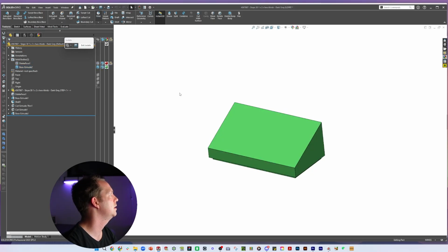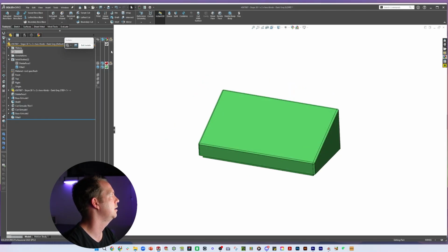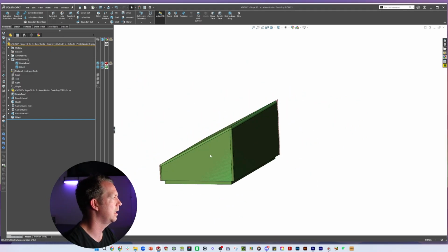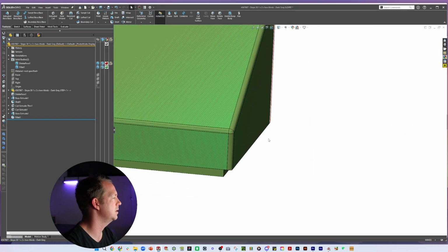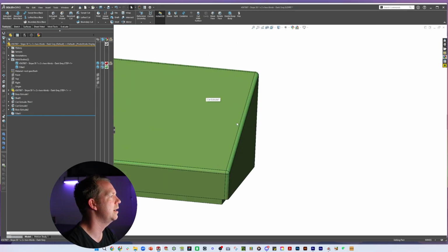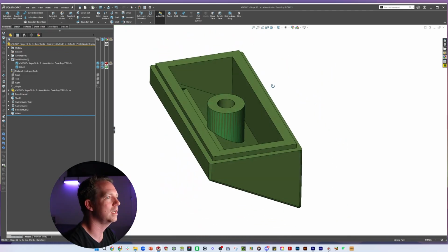So we're going to fillet 0.2 millimeter, select all of our edges, okay, exit isolate, and now here's a trick. We can see the difference because we deleted those fillets. We can delete that delete face feature, and now we should have a perfect match of the geometry if we followed all those steps correctly. And this looks pretty good.